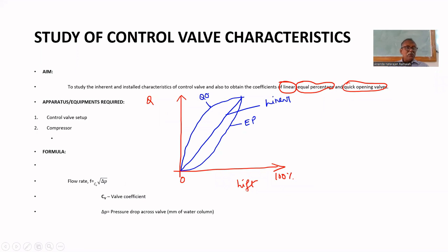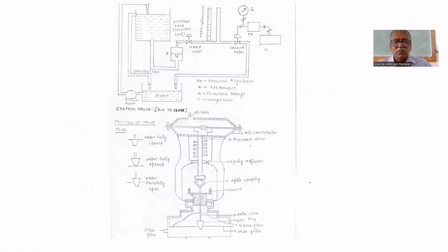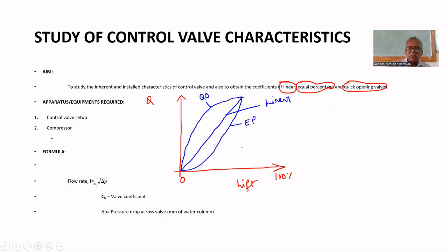This is true only when the pressure drop across the valve is constant. To understand the valve, this characteristic is called inherent characteristics.